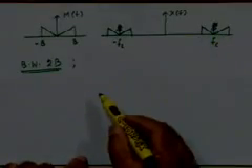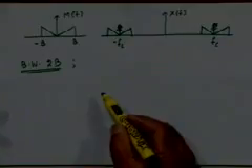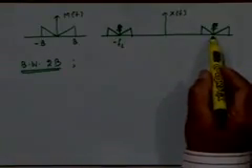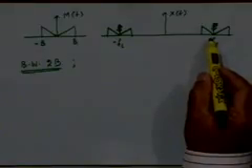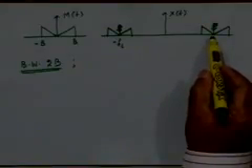But you can't say that there is a component at FC, right? There is a difference between that. You have to have some understanding of what a density function means and what impulses in the density function mean. When you have an impulse in the density function, that means there is a localized component at that frequency. There is some finite power or energy that we can talk about at that frequency.